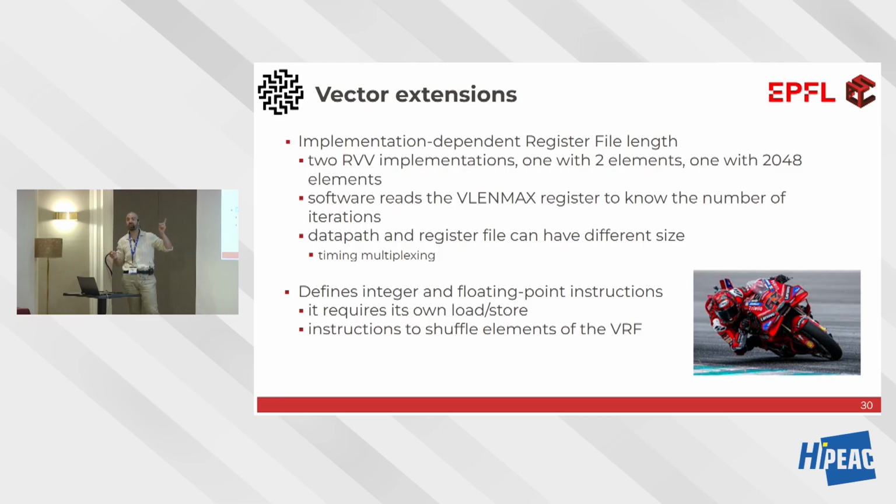That's specified in VLMAX. Who cares about the name? It's a custom register. It defines, in your custom CPU, how many elements you have in your register file. Tricky question now. If the two of us design RVV compliant RISC-V CPUs, my CPU has 8 elements maximum, and your CPU has 16 elements maximum.